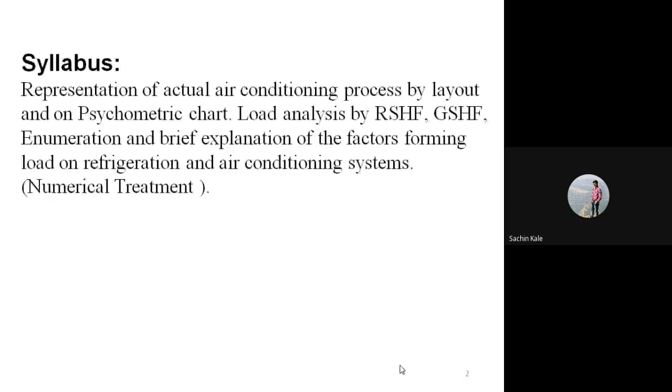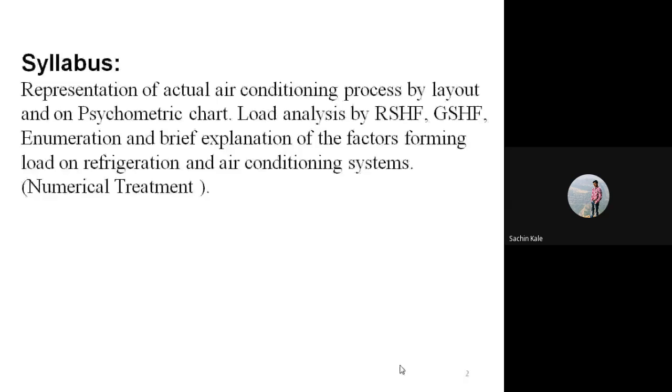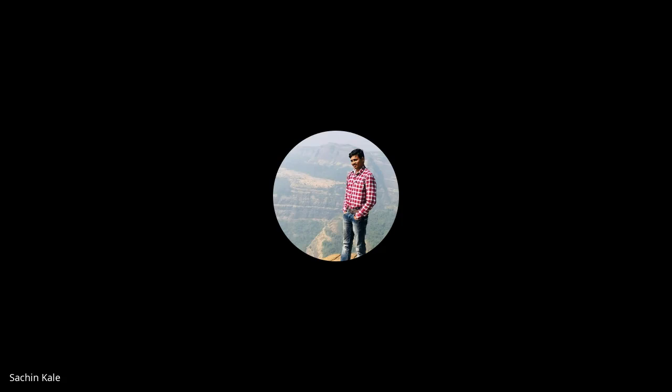Those are 3 formulae. After that, pV, enthalpy, those formulae, and rho V, that is air density. If you solve problems using these formulas, those are problems based on psychrometric relations. The second type is problems using the psychrometric chart. In the last lecture, as well as the lecture before, we solved problems using the psychrometric chart. In chapter number 6 also, whatever problems are there, we have to solve them by referring to the psychrometric chart only.